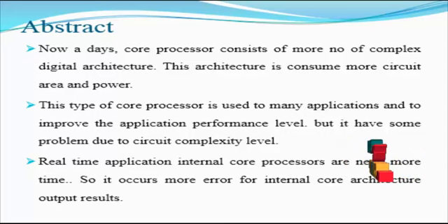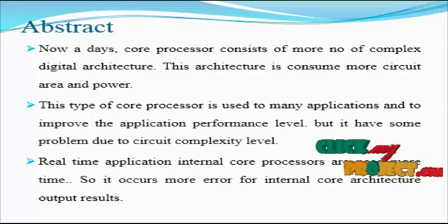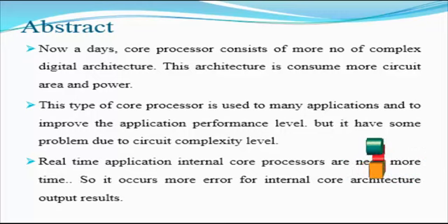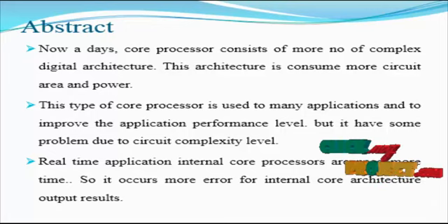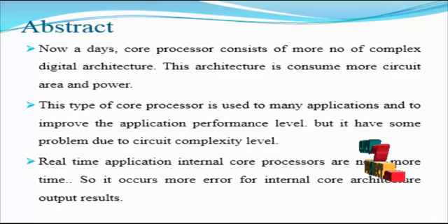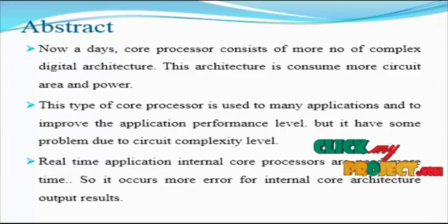In this brief, a novel fault tolerant technique is proposed by combining QL with QT implemented at the last layer of the circuit. In this technique, quadded transistors replace every transistor in the gates that produce the circuit output, whereas quadded logic is implemented for the remaining circuit. The implementation is therefore referred to as the quadded logic with quadded transistors technique, and it takes advantage of the gates and simultaneously serves as the voter or arbiter.